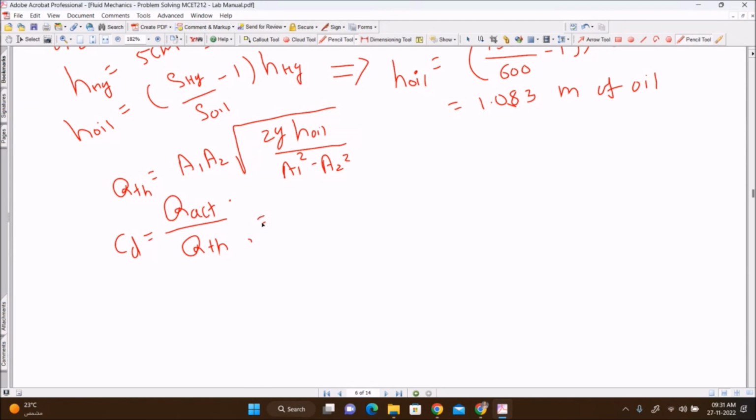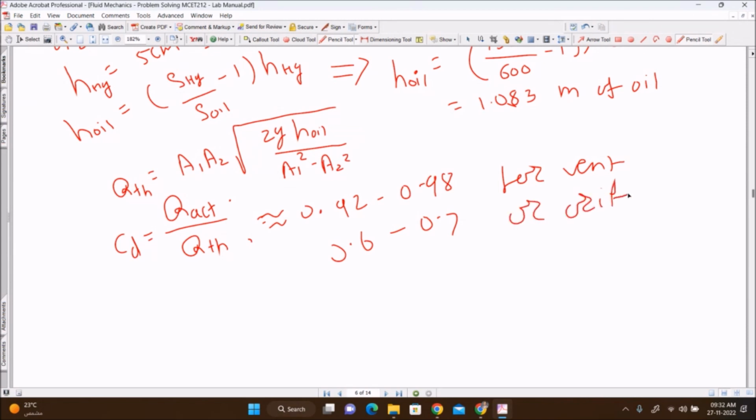Your value will be around 0.92 to 0.98 for Venturi and 0.6 to 0.7 for orifice, remember. You can write directly: actual discharge Q actual is equal to CD Q theoretical.